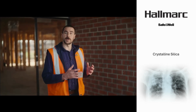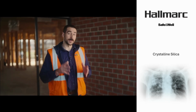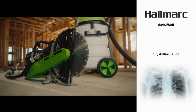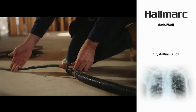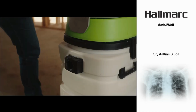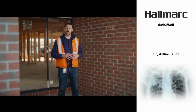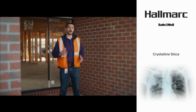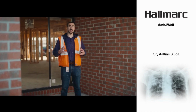An on-tool dust suppression system uses a continuous supply of water to control dust at the source. These systems are made up of a power tool or machine, a water source, a water outlet, often in conjunction with a shroud or a guard, and sometimes a vacuum. On-tool dust suppression can be used with a range of tools and machines, including saws, grinders, corers, jackhammers, and excavators.